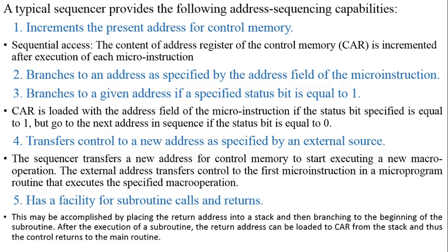That means if we want to start a particular macro operation or a microprogram routine, we want to specify the starting address of that microprogram routine from an external source. This is mentioned by this fourth method of sequencing.